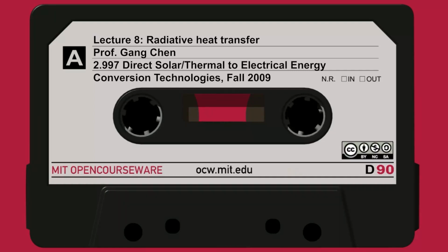Now I want to calculate the solar constant. Like I said, 1366. I want to check the radiation reaching the Earth from the Sun. So this is the black body emissive power of the Sun, if I approximate it as a black body, times the surface area, the disk area A_S, times the view factor from the Sun to the Earth.